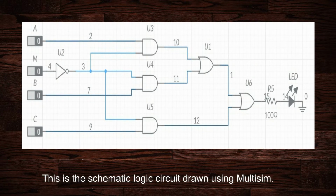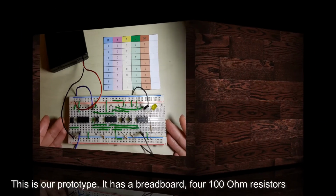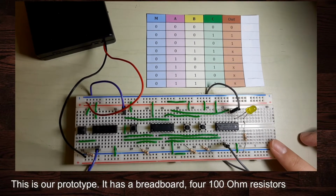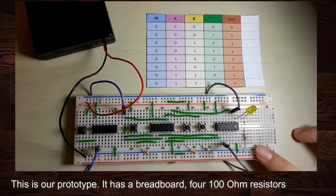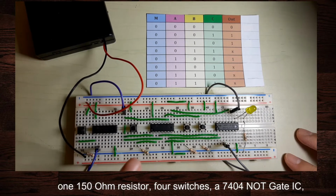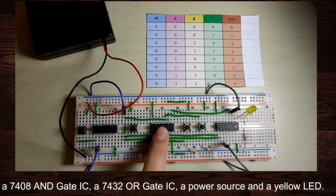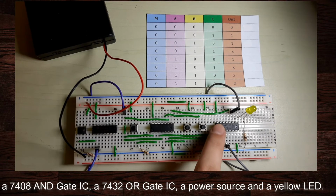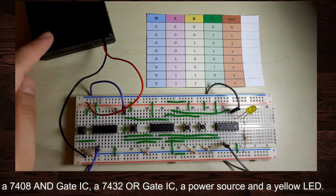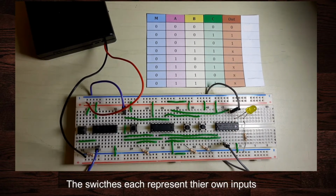This is the schematic logic circuit drawn using MultiSim. This is our prototype. It has a breadboard, four 100 ohm resistors, one 150 ohm resistor, four switches, a 7404 NOT gate IC, a 7408 AND gate IC, a 7432 OR gate IC, a power source, and a yellow LED. The switches each represent their own inputs respectively.